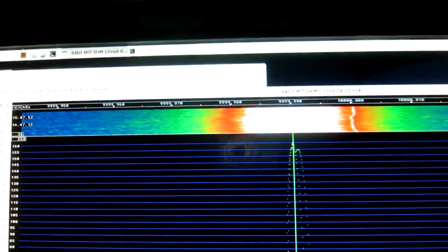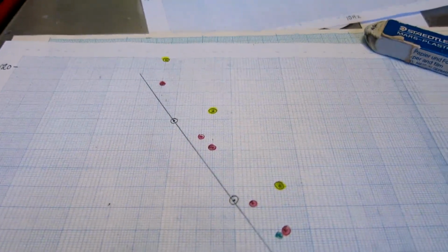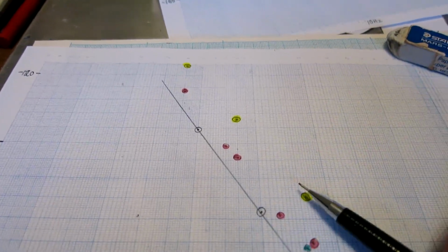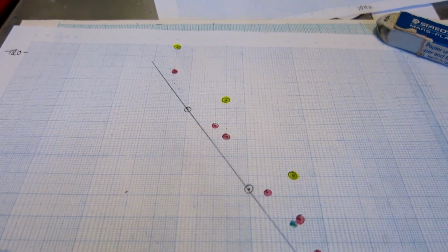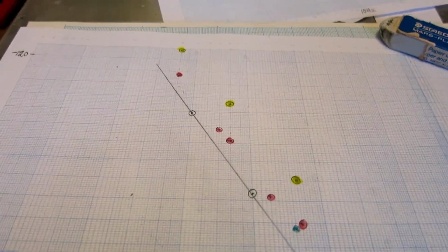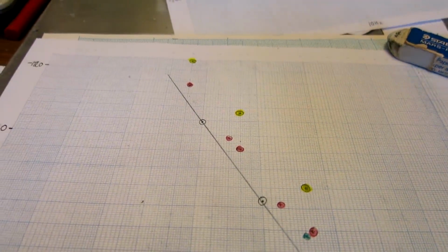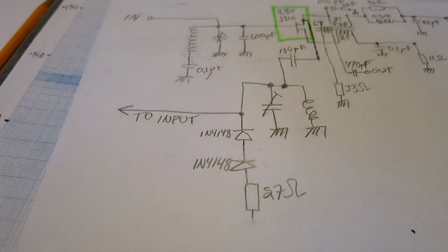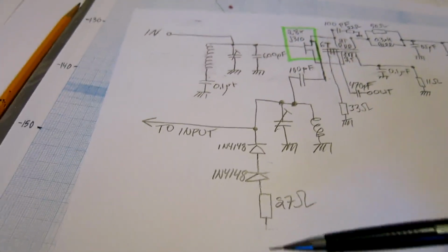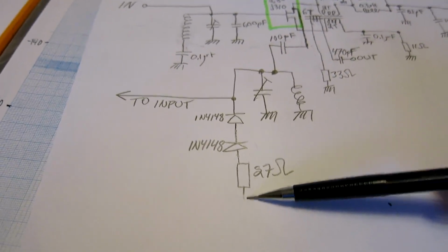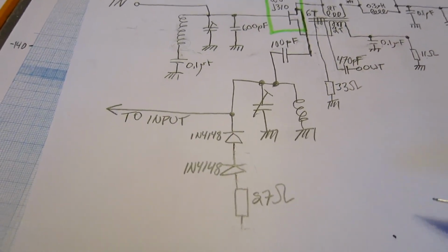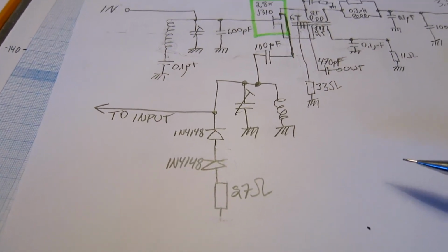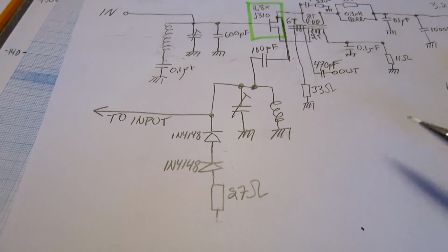So I save this at 4 dB lower power. Noise is about 4 dB higher at close range, and of course also at wide range. So it seems I should instead increase the power. I have disconnected the resistor here from ground, and now the oscillator runs with compression in the amplifiers, and the power level is about 2 dB higher than it was originally.